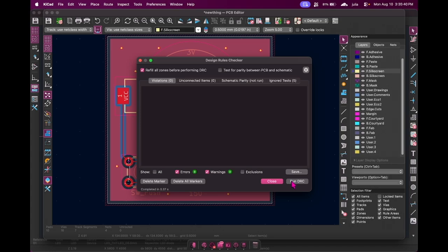You guys can make PCB art, but not with vias, with silk screen. You can make images if you like. There's a specific part of KiCad. You'd have to search it up because I don't remember off the top of my head. Sorry, it's silk screen image. It takes an image and lets you use it as silk screen, and then you can put it in your PCB. You can put any image.